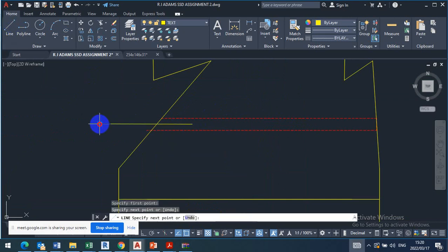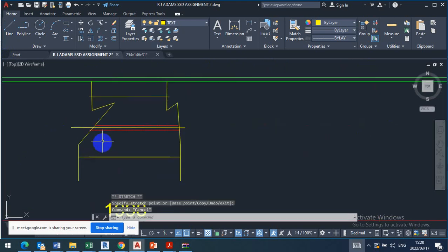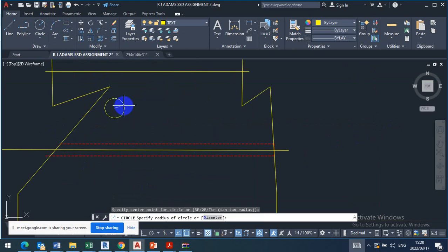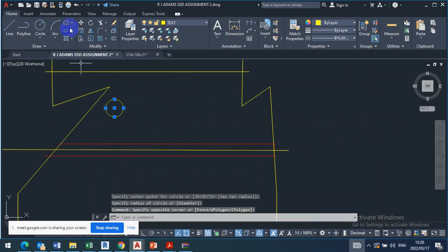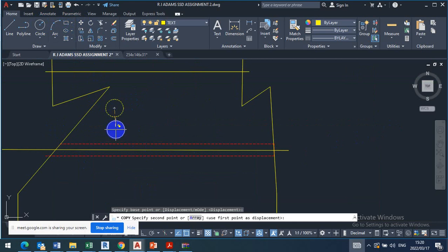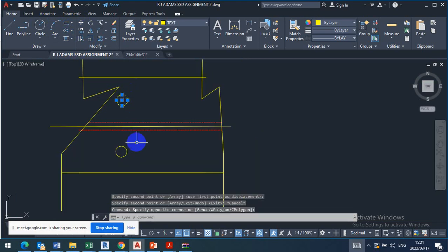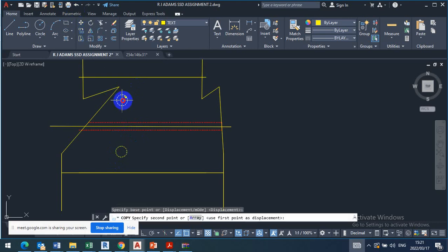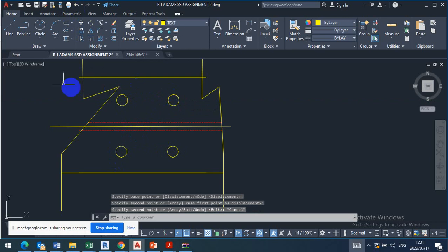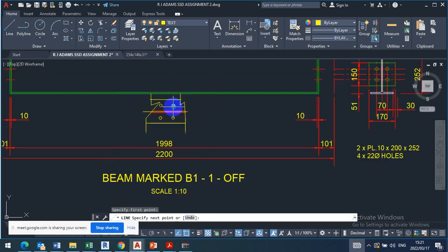I'm just now working fast. If this is my center line, it means that I need to offset 35, 35, to show the position of the holes here. In that case, whichever way 35 is going to be, maybe it's here. You're going to show this hole, then copy 70 down to that side, whichever, 70, and then you copy pitch. You can work with a pitch of 70 or 140. If we work with 140, then the examiner wants you to show the center line from here.